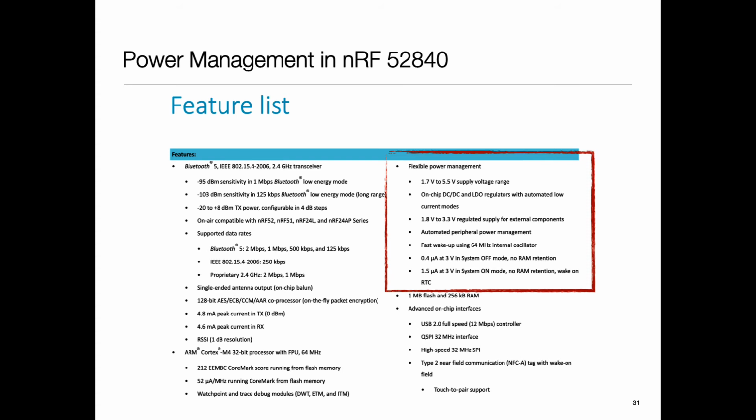Now, why does the wake up time come into play? So I alluded to there could be circuit reasons and there could be software reasons. Circuit reason simply is that some of the circuits have capacitors, or they may be kind of like mechanical devices, like you had mentioned crystal oscillators. Crystal oscillators is piezoelectric crystal which vibrates.